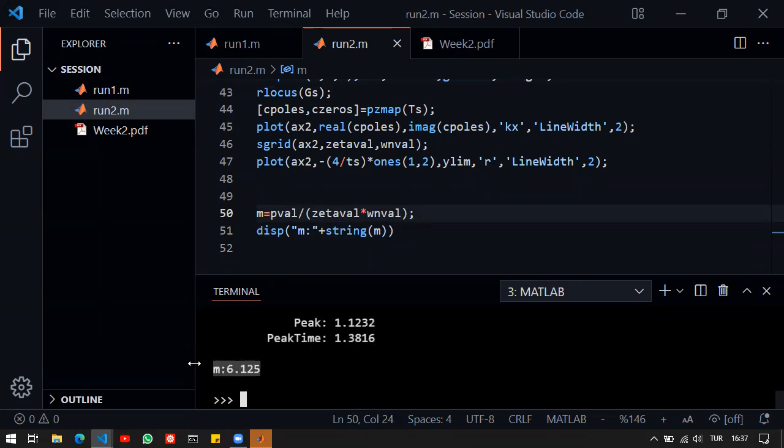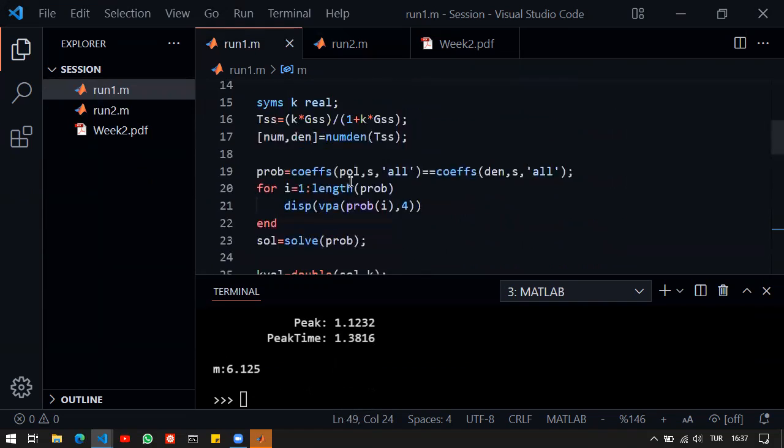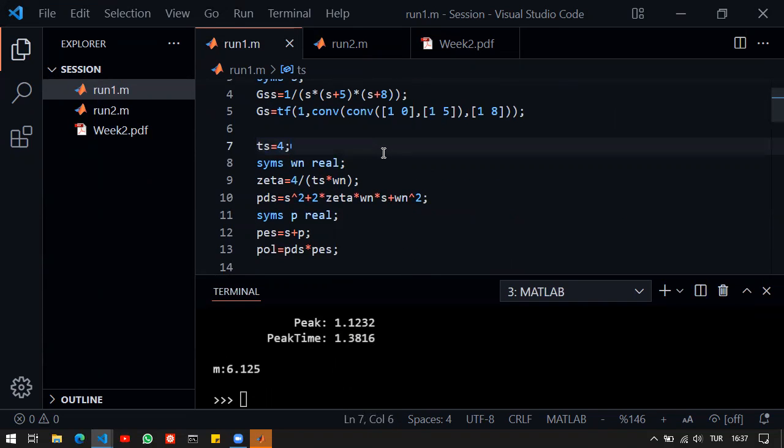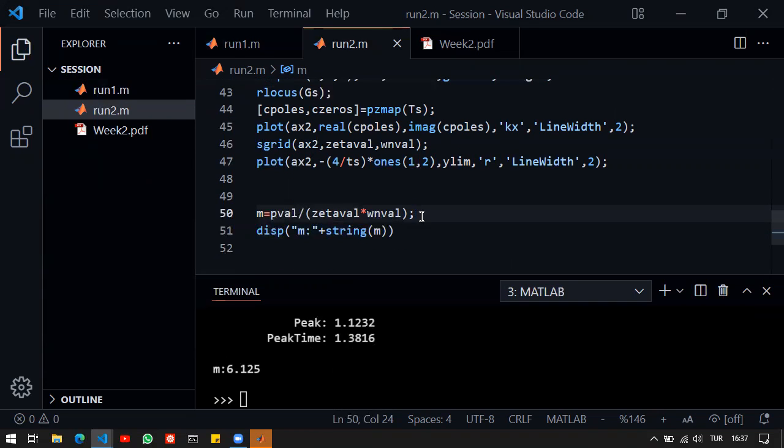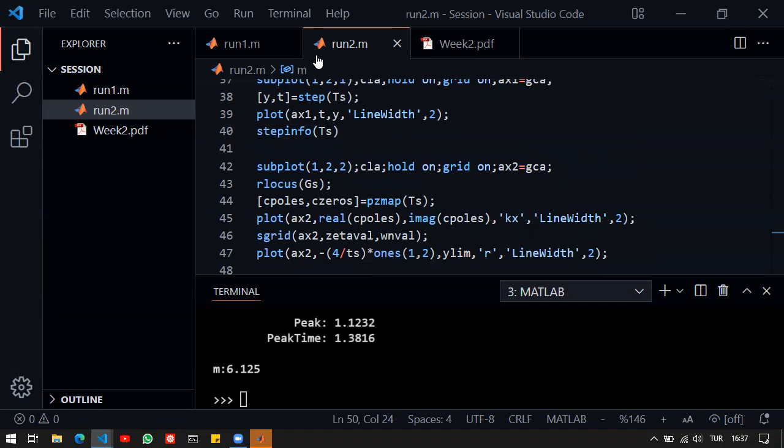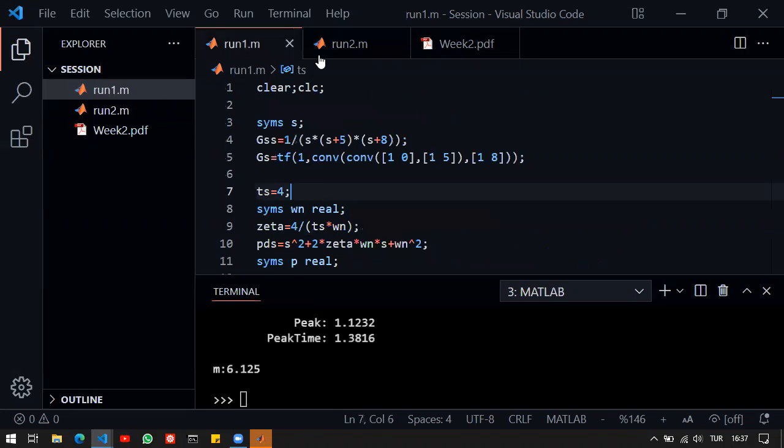So this is basically showing me that my solution is almost good, is a better solution, etc. I can directly tell you that this solution with settling time 4 has a better dominance factor, or sticks more to the dominant behavior, but this one deviates a little bit because we have a lesser dominance factor. It's not far enough. We couldn't place P far enough in order to have a better accuracy. But it's still okay because of the fact that 2.5 and 2 are at least in some range. It could have been worse.